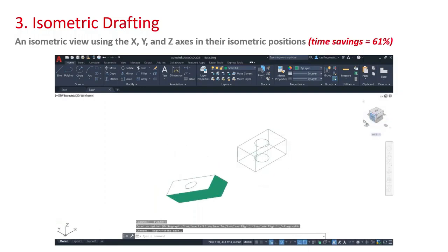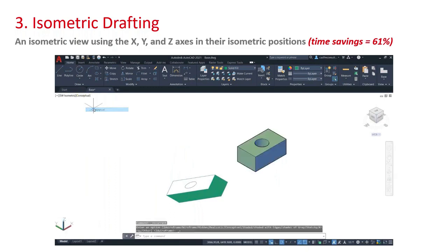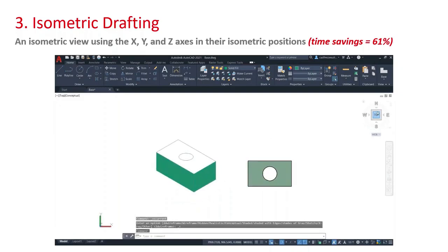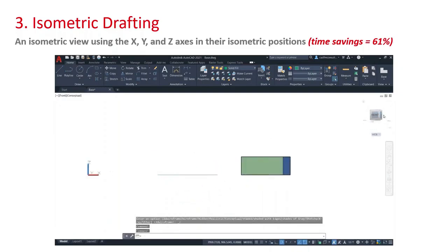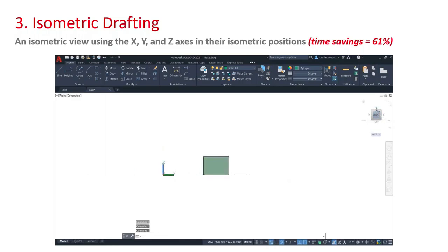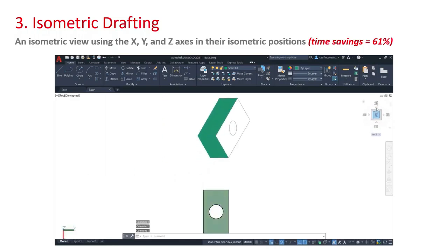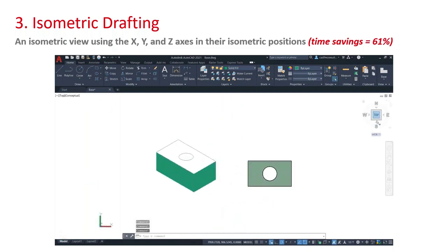Now, if I jump over to the view cube, you'll see now we've got a 2D wireframe view of our solid base. If I go to conceptual, you can see that that is a solid. And if I look at the top, I'm looking straight through it. There's a hole through that solid. And just like in the previous video, you can see we can jump around and pick any view we want on the view cube to look at our little rectangular base with the hole in it.